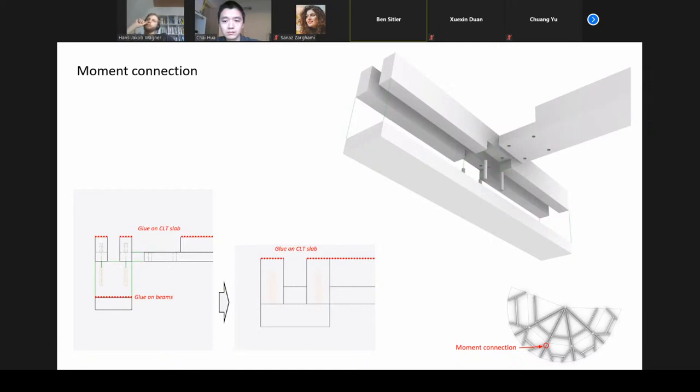But if you were to look at how to do this in practice, I feel like using larger beams, maybe larger than what the robot for this workshop can handle. If you were using this as a case study of what could be done in practice, you'd probably want to use LVL sections that are available. From the suppliers that I've seen, they have some minimum dimensions.